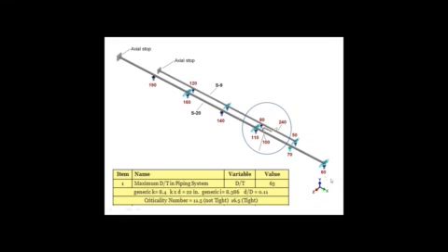We go next to the next system here. This is another typical problem where you've got long sections of pipe and small crossovers. The SIFs and the flexibilities here, when the piping is tight, can be important. Here we see D over T values of 63, with criticality numbers of 11 and 16 if it's tight. That's a little bit over where we want to go.